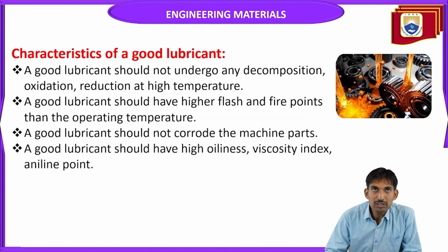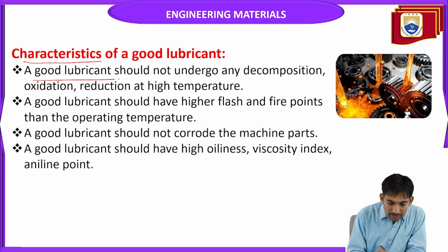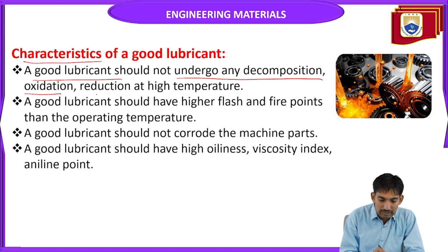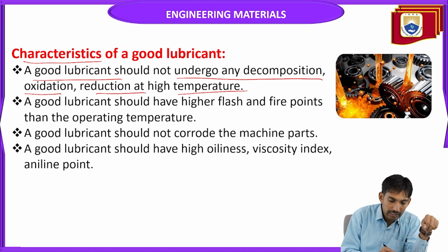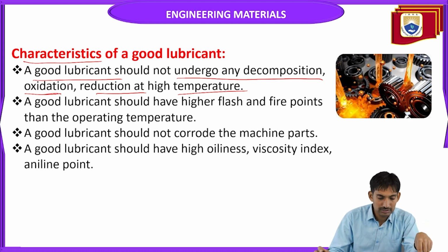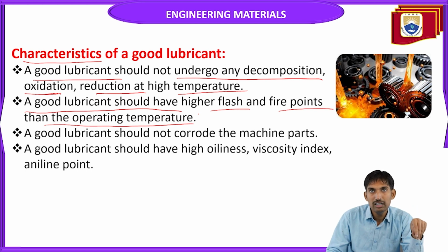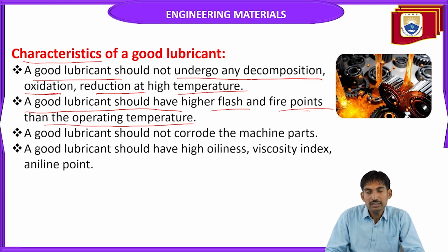These are the characteristics of a good lubricant. A good lubricant should not undergo any decomposition and oxidation reduction at high temperatures. A good lubricant should have higher flash and fire points than the operating temperature.